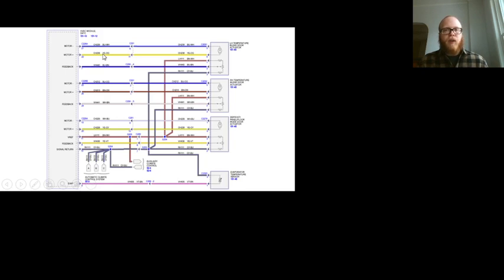Here's a diagram showing my actuators. So here's my blower motor actuator right here. The HVAC control module changes polarity depending on which way it wants the actuator to move. And then it gets feedback on this wiper signal wire feedback. As it moves, this wiper mechanically moves across the resistor, and the voltage that is received at the module changes, and it's able to interpret those different voltages as what position the door is placed in.